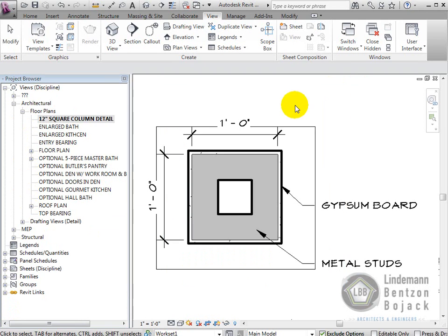In Revit, there is a file called your shared parameters file. What that allows you to do is to make unique fields that can be applied in your Revit model. So I can make a unique field a property of a view or a property of a window or a door. It could be anything.